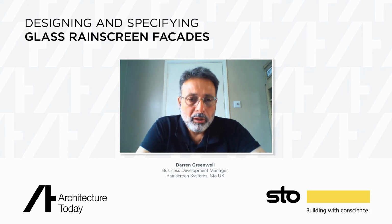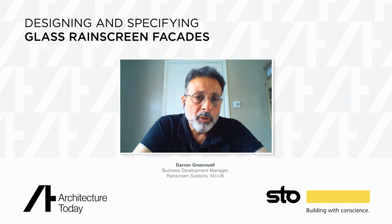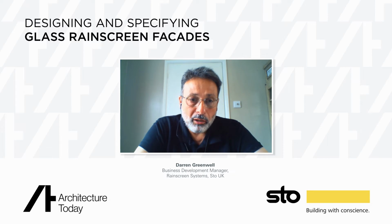So the internal skins: how thick is the plaster or plasterboard on the internal skin, how much lightweight steel frame and insulation is in the stud, what sort of sheathing board is on the outside, that full build-up. Then we can calculate a U value and say, right, you need 100 mil, 150 mil, 200 mil of insulation. Once the amount of insulation is established, then we can look at the subconstruction.